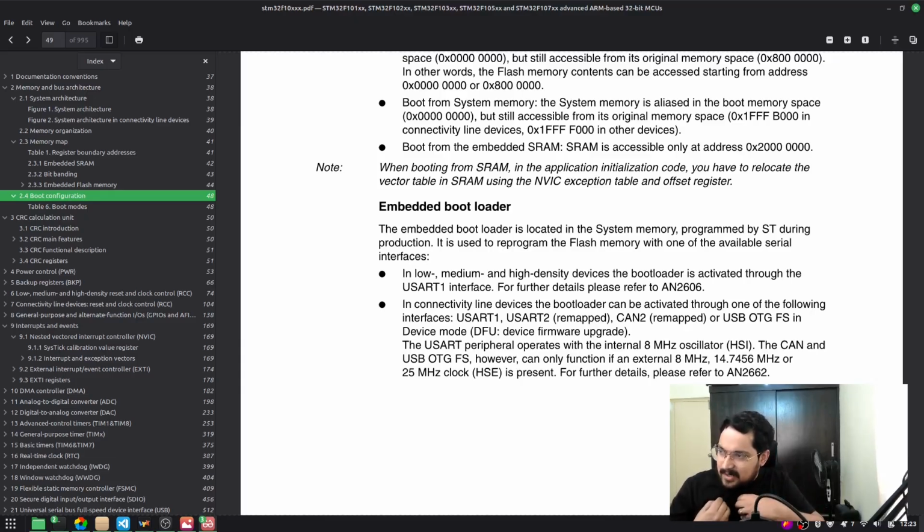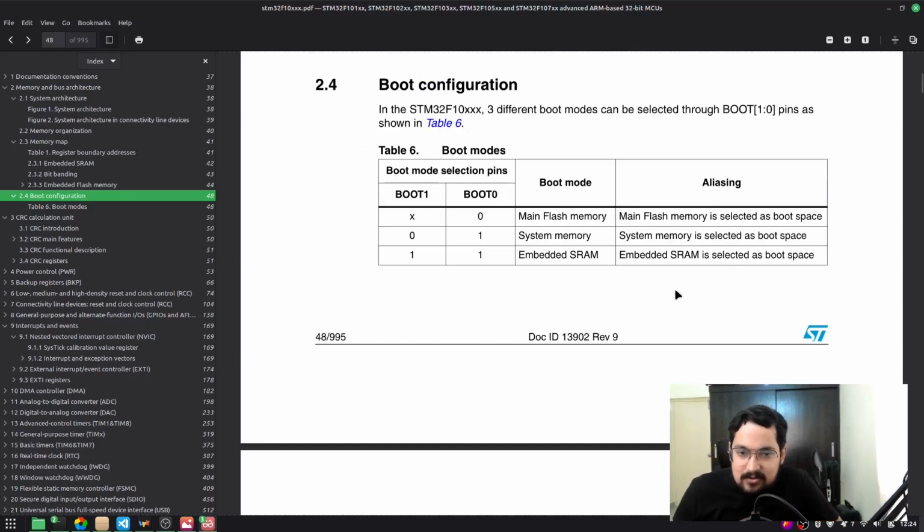Unlike our bootloader, which is eating 8 pages of memory, this bootloader has entire access to flash and can also work in various modes like DFU, USART, CAN, etc. But the thing is, you have to physically set your boot pins this way, and it's not fun. You don't get to learn how the bootloader is working. This is also fine. It has its application. Therefore, we'll call it a custom bootloader.